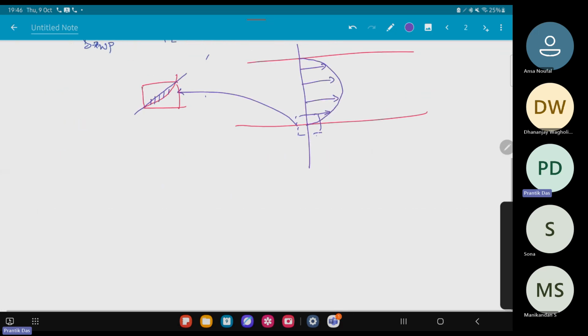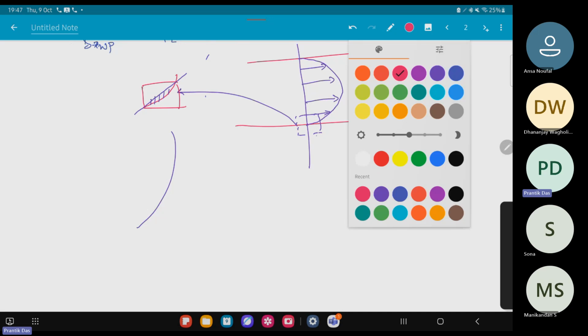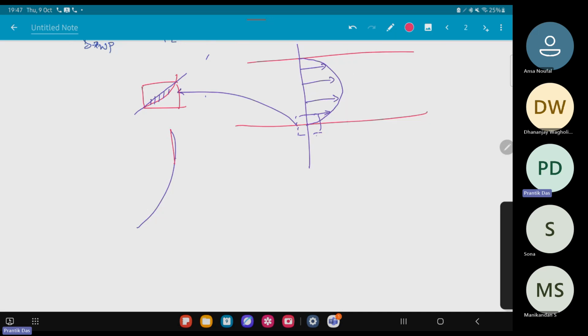So this quadratic function can be assumed to be an overlap of linear lines. If I take the cell to be very small near the wall region, the quadratic profile can be assumed to be a combination of linear lines.